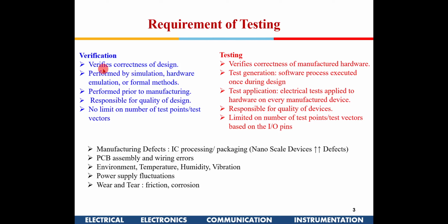Suppose you have a 64 bit adder. Does verification involve 2 to the power of 64 plus 64, that is, those many combinations? Do you have to check all of them? Is that possible? It may not be possible, so there is a science to it. Verification also has to be done judiciously. I will touch upon that in the subsequent slides.